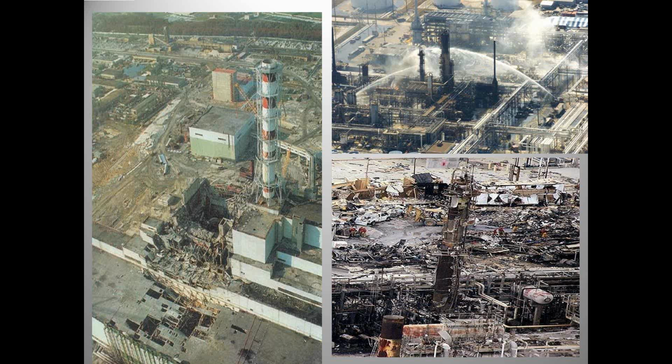There was a high-level transmitter above the level transmitter that didn't work. So, long story short, the column fills all the way to the top. It overflows to a flash pot, which is a little tall skinny stack on the right center part of the picture. The flash pot's got a level probe in it, which should have lighted the flare and burned the chemical off, but that level transmitter also didn't work, so the flare spewed liquid out of the top. Some maintenance guys taking a break in a pickup truck down below actually ignited it, and it killed 15 people.